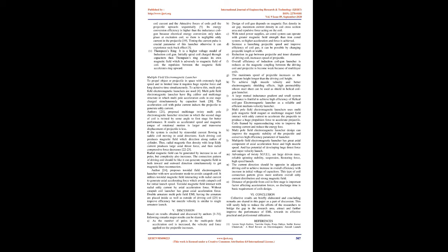Induction coil gun launchers are basically differentiated as follows. A. Asynchronous. The driving coils may be connected in series or in parallel and energized with a certain time sequence. The relative movement between the projectile and the traveling wave induces current in the projectile. B. Synchronous. The driving coils are stacked end to end and energized sequentially to provide an impulse force to accelerate the projectile. The velocity of the projectile is exactly equal to that of the electromagnetic traveling wave.